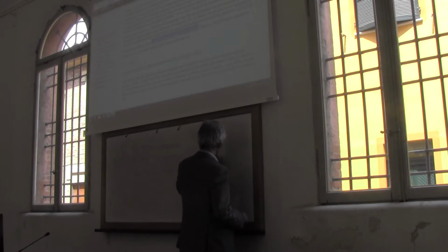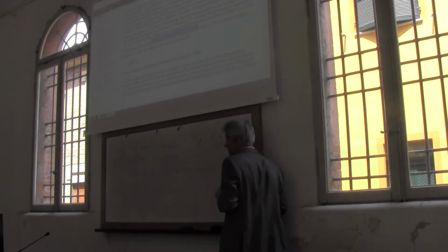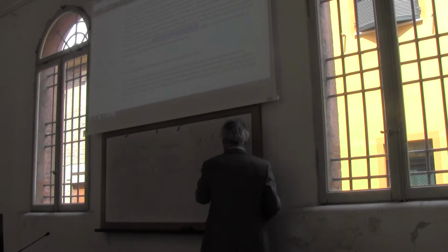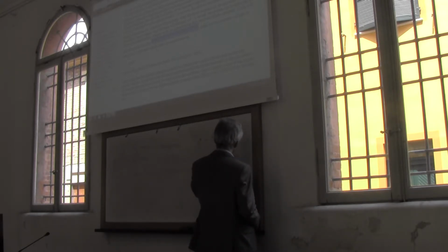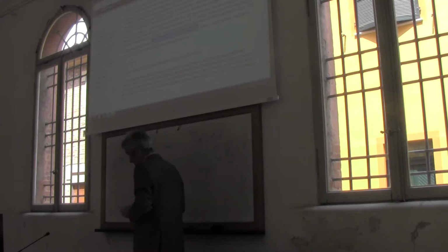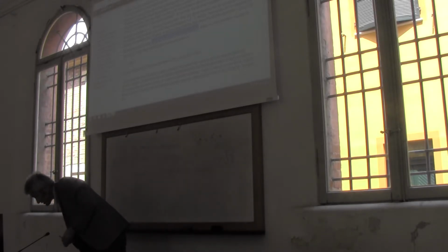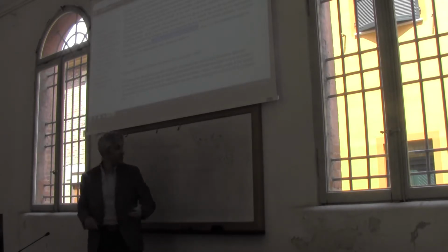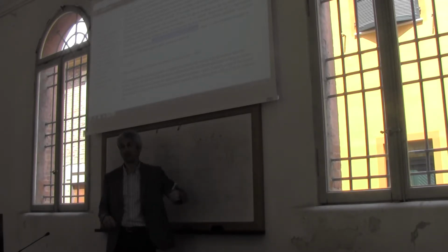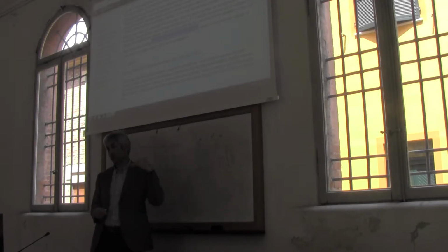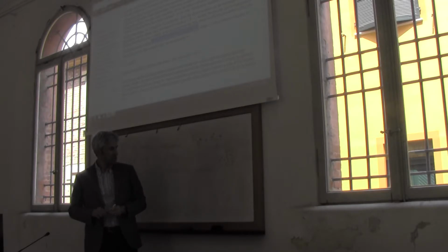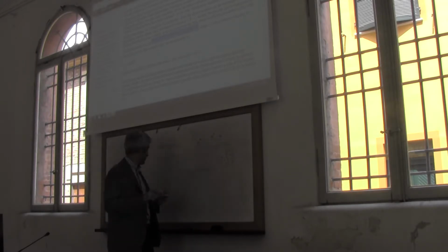So, what is u star? It is the shear velocity, which is a characteristic parameter that we can express as the square root of the ratio between tau and rho. Let me see if the symbols are coherent. Yeah. Rho is mass density of seawater, tau is friction. Friction can be estimated once we know the wave behaviors. Okay, so what can we write?